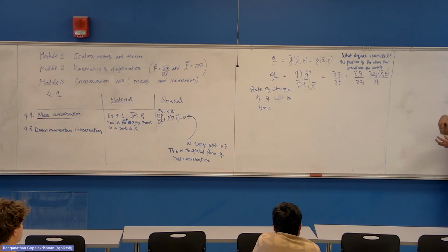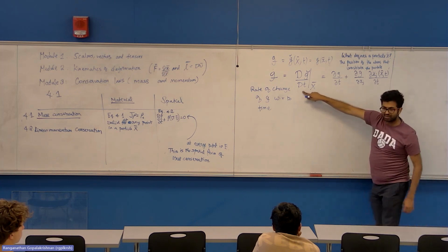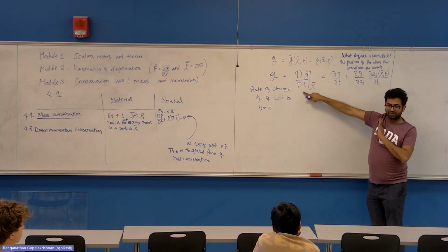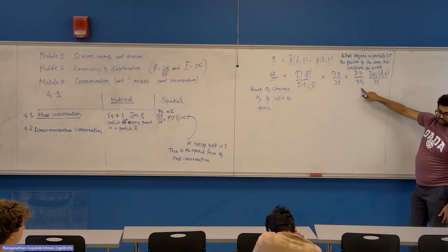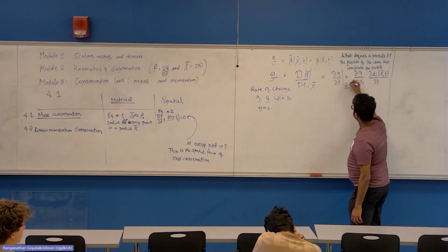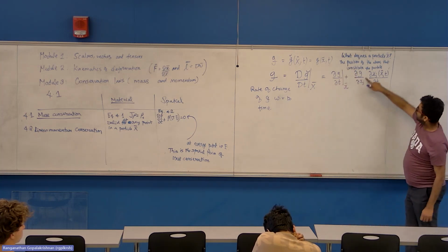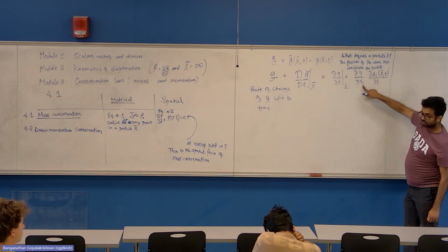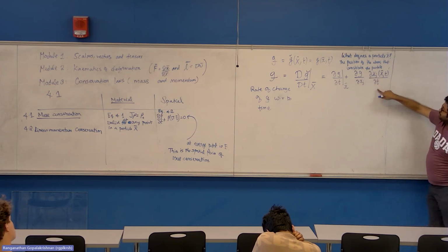So if your particle has deformed into such a shape that it looks like a donut with a hole in between, your particle is the donut, but not including the gap in between. That is not your particle, even though that volume is between your particle. So this calculation is actually very difficult in practice, which is why we never do it. We switch back to the spatial form where you can get a derivative of g with respect to time for a constant position in space, multiplied by the derivative of g with respect to the position, multiplied by the rate at which the position is changing.